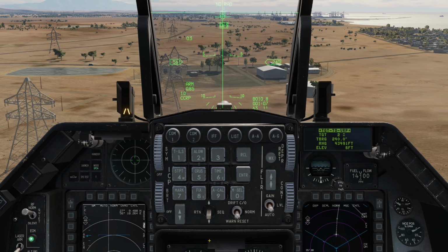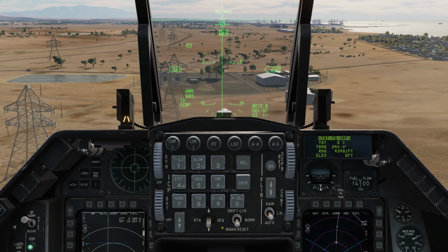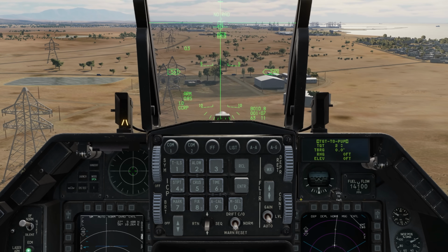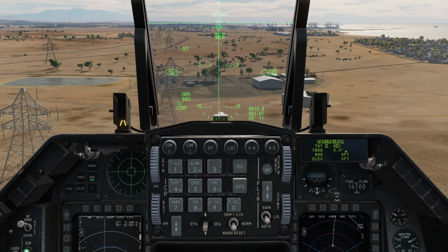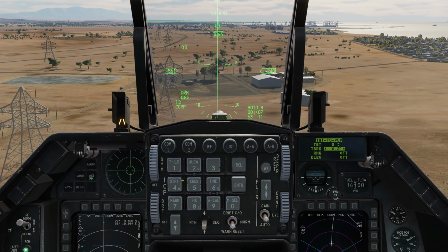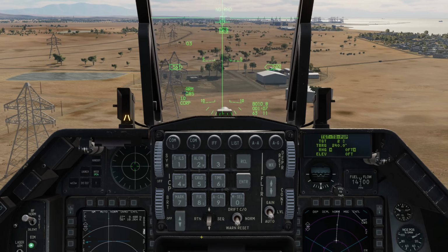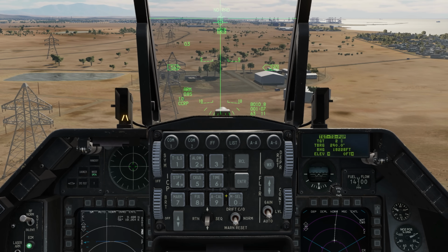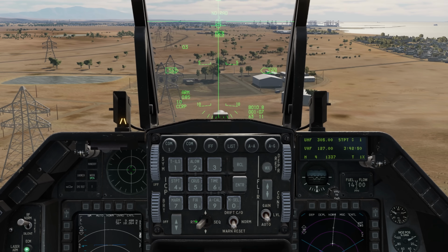Now, just like we had for VIP, we also have a PUP option for VRP. To do that, just like before, we'll go right on the dauber switch, target to PUP, M select to enable, dauber down. It's already set to steer point 2, which is the target location. Dauber down again, target bearing 2400, enter. Range, I want to be about 3 miles, which equates to 18,228 feet. Elevation of 6 feet. Down, back to the CNI.